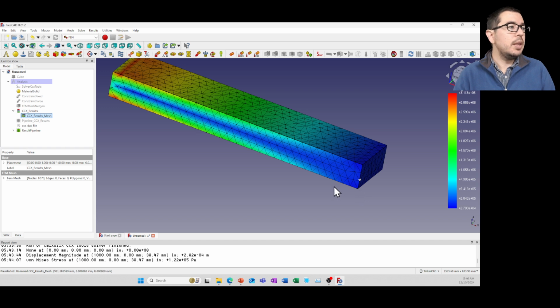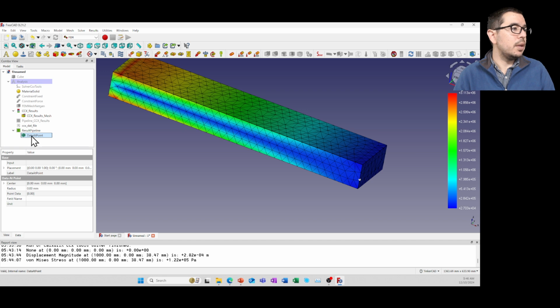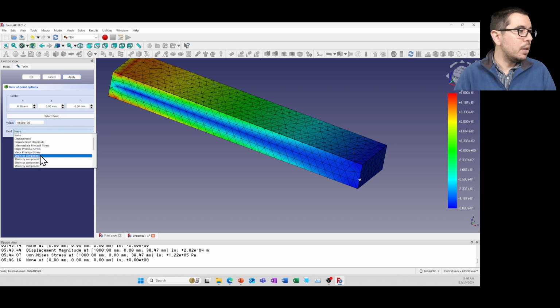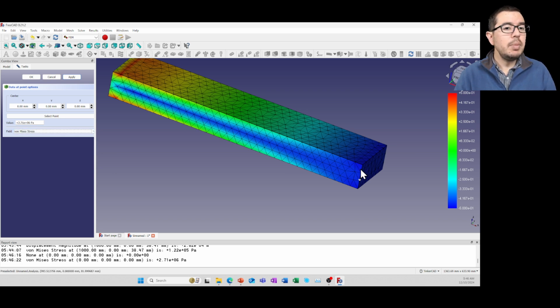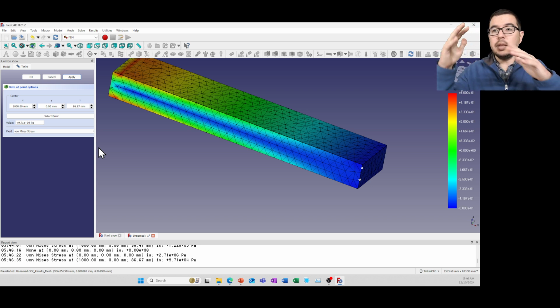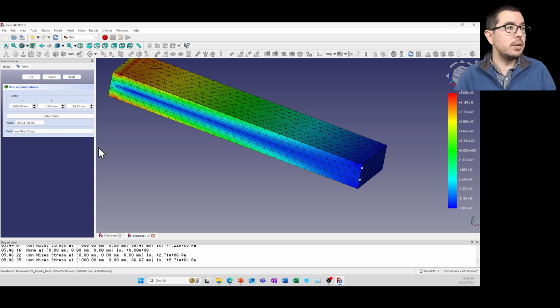Okay, and so if we move up, let's go back over here, and double click here. If we click another point, this has got no field, and we'll just do the von Mises stress. If I move up a little bit, I should expect that now, so that was at 0.2 megapascals. If I go up to here, it went down. So now it's at 0.09 megapascals, because I've moved away from the longitudinal axis, and I see that my stress value is different.